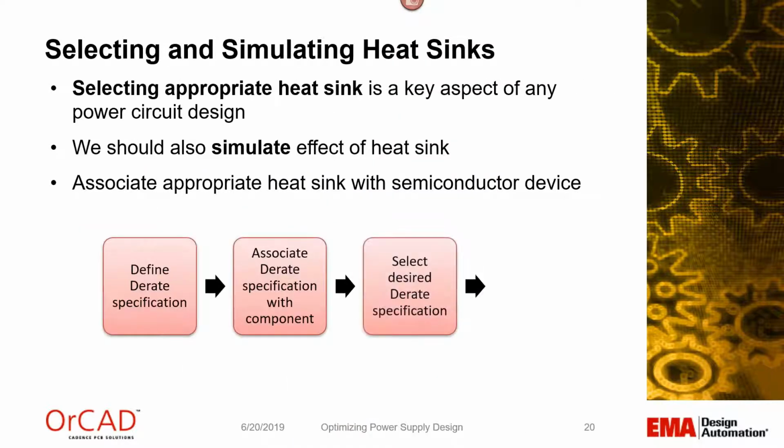So let's move into the realm of heat now. We've talked a lot about picking the right components, but an underrated factor for power supply failure is overheating your components and overheating your design. Your capacitors, your inductors, your MOSFETs, the controller itself, their behavior might change as your power supply heats up. So if you're going to be using heat sinks, and many of you will, make sure to model the effects of those heat sinks on your simulation.